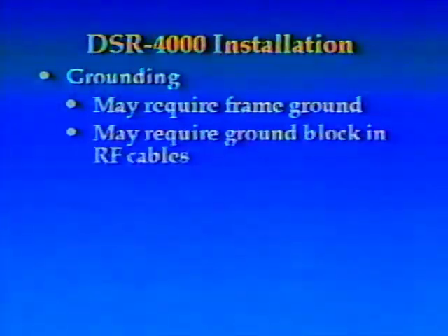They are designed so that the RF, case ground, signal ground, and power ground are all separate and they all float. Now this is good engineering practice so you don't get ground loops. However, if your rack is not absolutely firmly grounded, you may have to supply a ground directly to the IRD case. This is something that you need to be aware of.